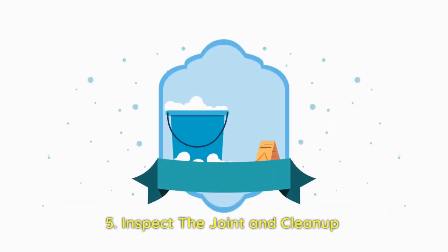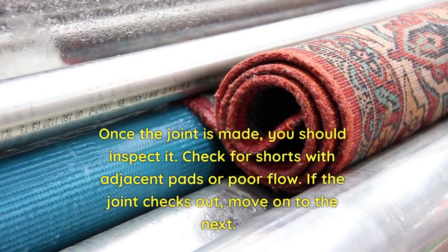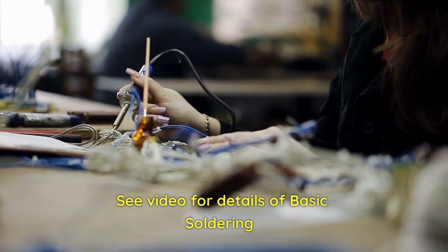5. Inspect the joint and clean up. Once the joint is made, you should inspect it. Check for shorts with adjacent pads or poor flow. If the joint checks out, move on to the next. See video for details of basic soldering.